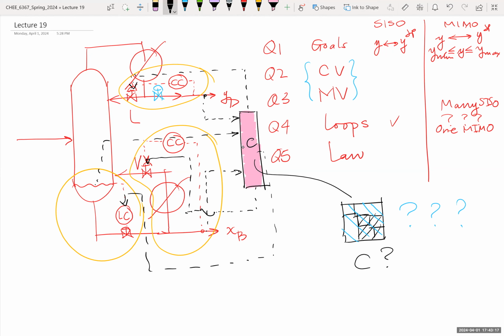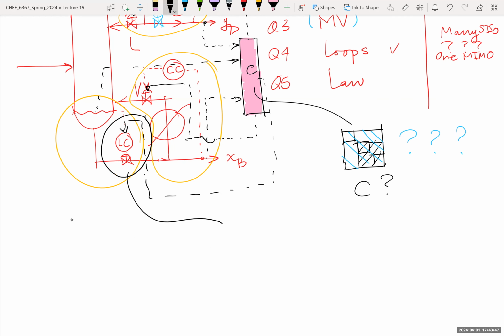Typically, this controller will determine these flow rates that will have to be delivered here. Of course, we have seen this a number of times for cascade and feed-forward control. We'll see these things in a bit more detail, but I wanted to start the discussion now. So essentially, this computer may send a command directly to this control valve here, or this may be cascaded.